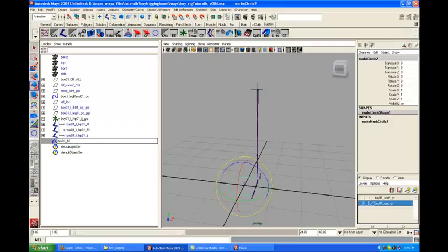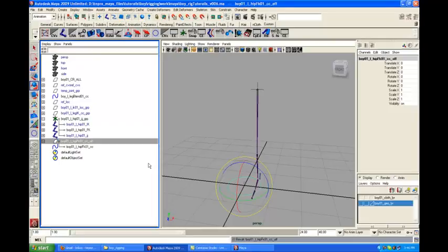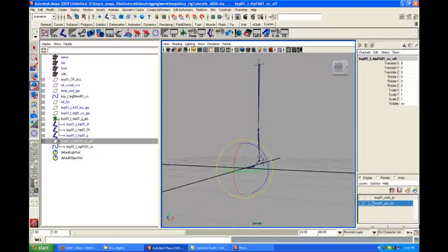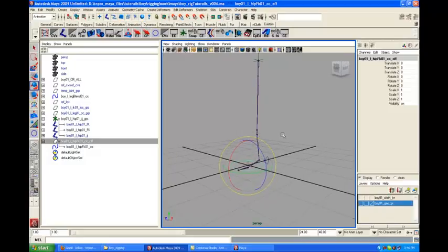So what we are going to do is rename it BOY01_HIP_FK01_CC. We forgot the prefix, it's on the left side. Okay, let's group it, Control C, Control V, and let's offset, because we don't want to have any value up here, so we're creating this offset group.